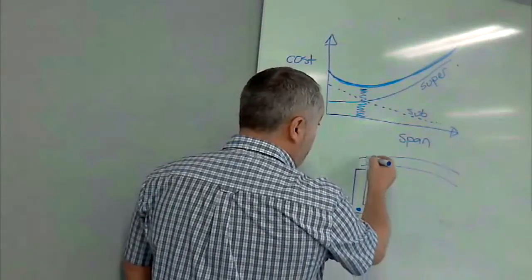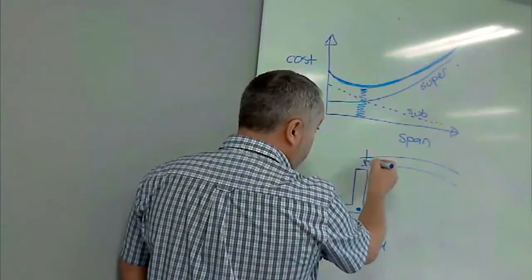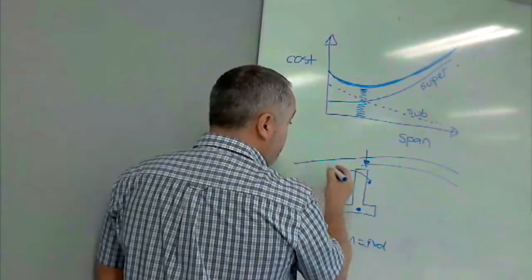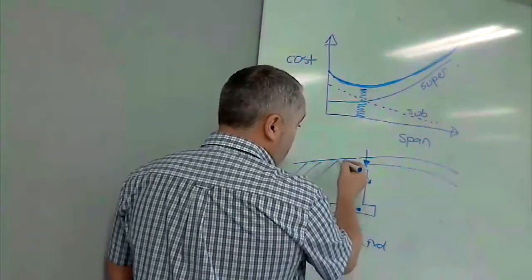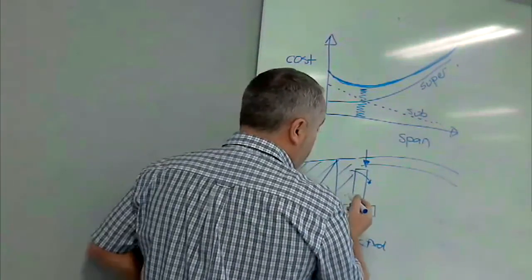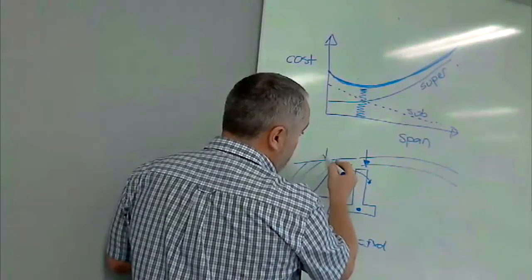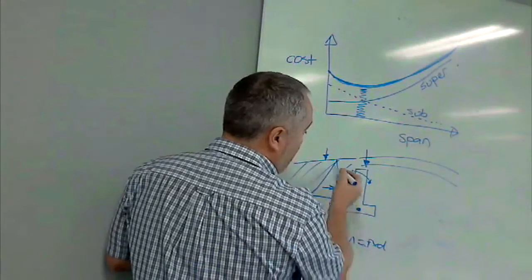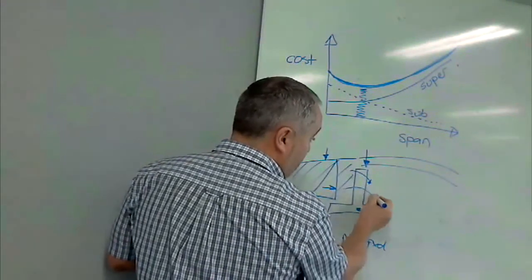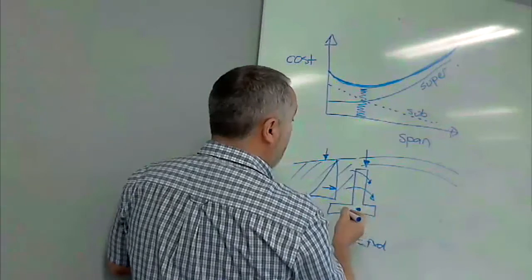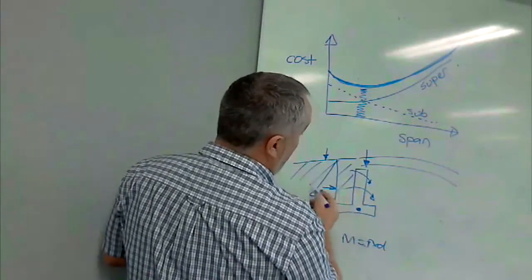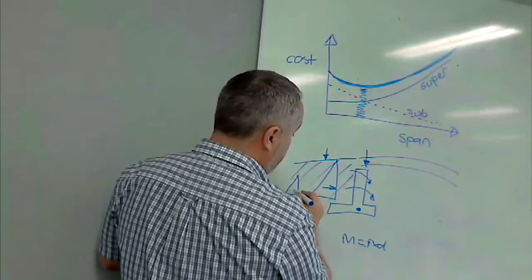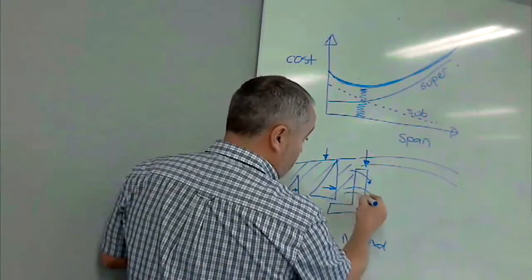So in terms of load, we've got the load of the bridge, that's trying to rotate it that way. In terms of the ground material, that pushes down like a triangle. So all of this load is transferred about a third up. The weight of material pushes this way, and that's trying to rotate the whole thing clockwise. And also you have any groundwater, so there's a hydrostatic pressure that is also trying to rotate it.